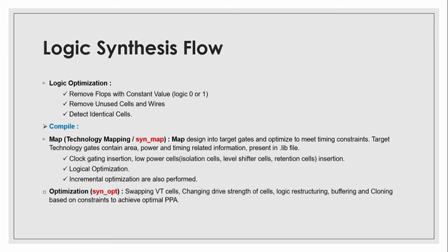So we can restructure logic to optimize the area and the design. We can also do buffering and cloning based on the constraints to achieve optimal PPA.